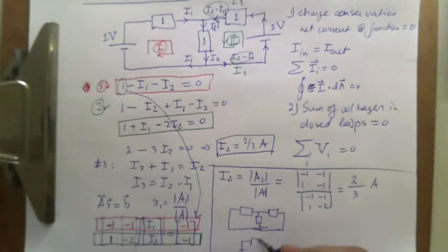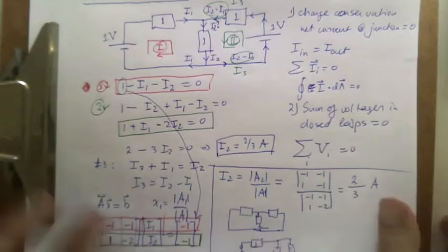And there's one resistor, and then there's two resistors in parallel. And the current I want to know is the current in this branch. That's this current. And if this is one, this is one, and this is one, the equivalent resistance of this is 1/2. And the equivalent resistance of this is 1. And then you can just work out what the current is.